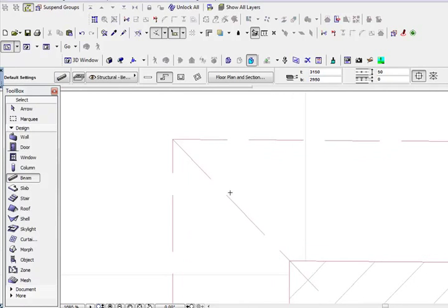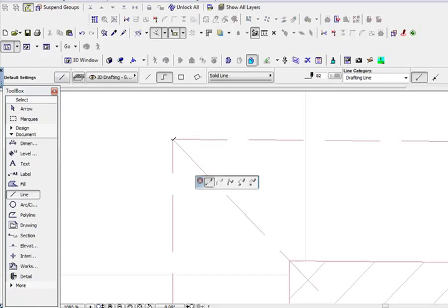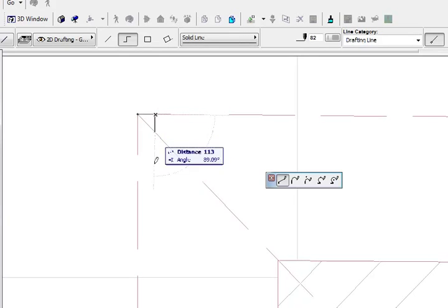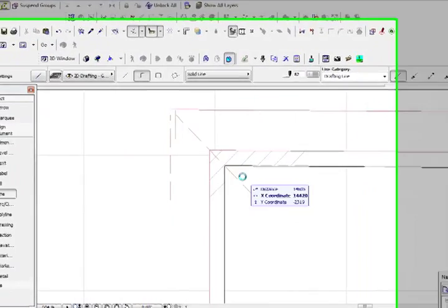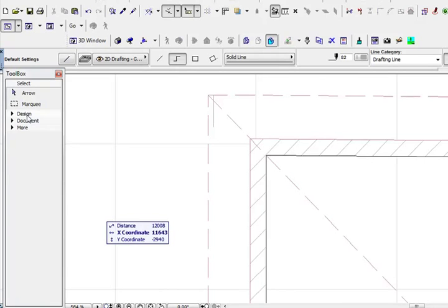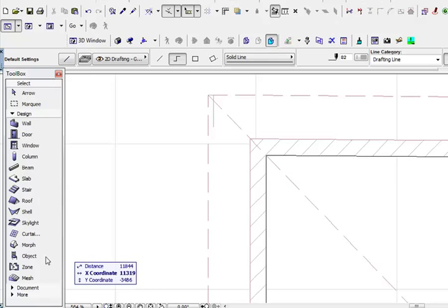Now there is a rule for this. It is always good to allow your roof to project like 75mm beyond your fascia board. That is how it is in real life. So it is always advisable to do it that way also in 3D modeling.